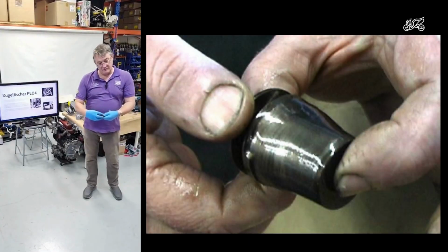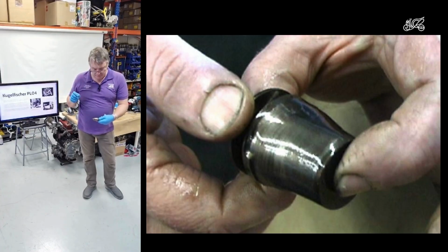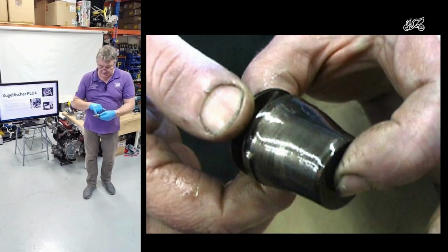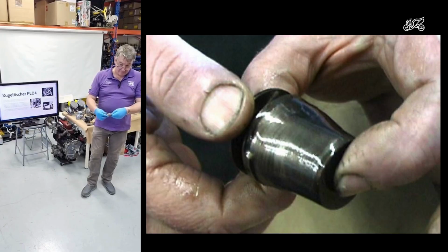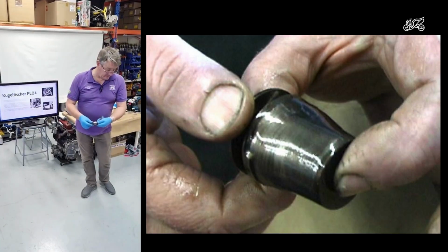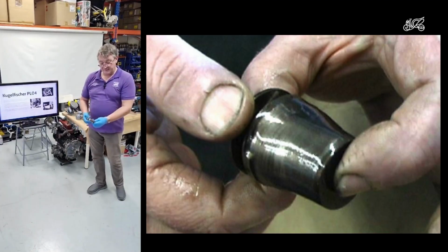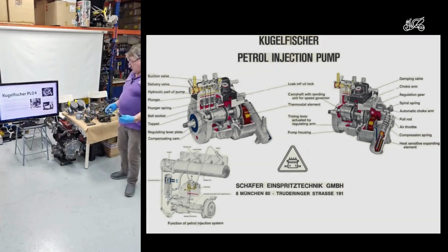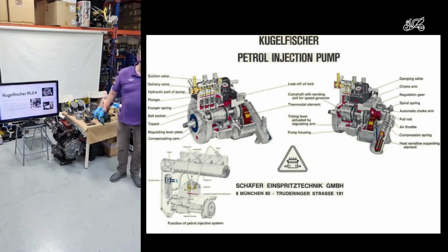And this cone is actually much bigger than the way the Bosch pump works. It doesn't use a cone; it uses just a simple, call it two-dimensional ramp. It doesn't have the same three-dimensional approach. So these pumps, by comparison with the Bosch pumps, were quite simple, a lower cost, and therefore got more mainstream use.